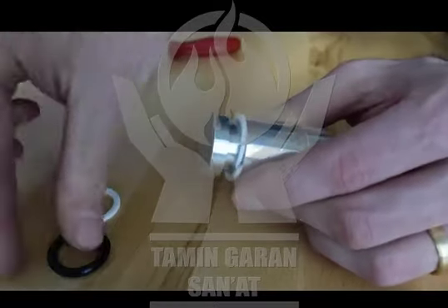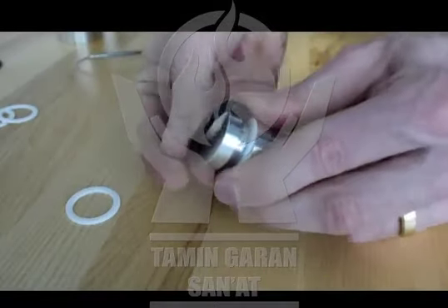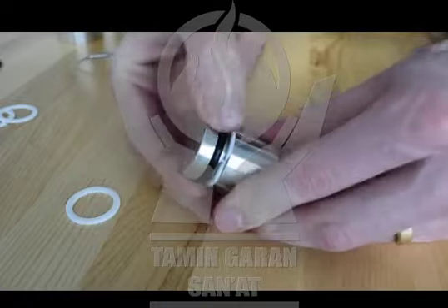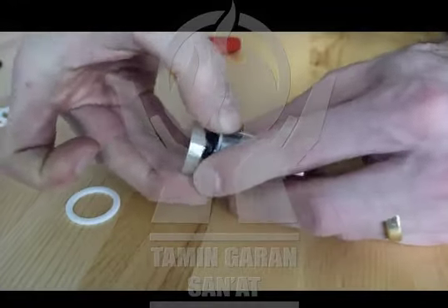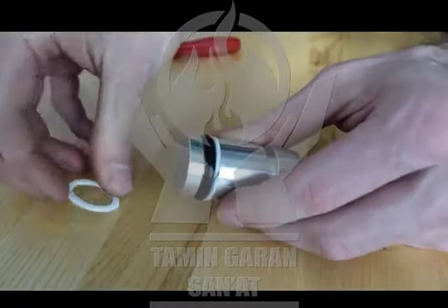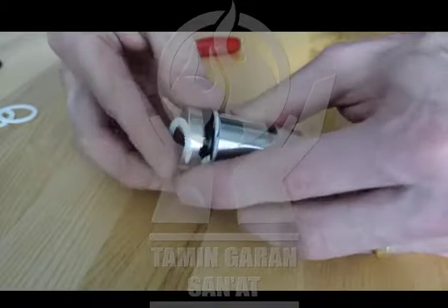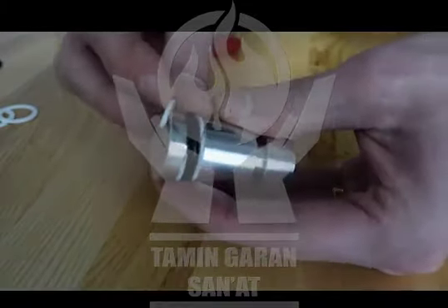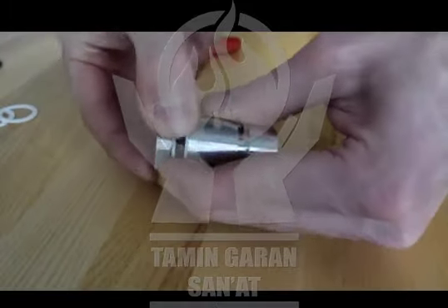They're made of a plastic like PEEK or Teflon, and they usually have a scarf cut to help you install them in the gland. Technically speaking, if you only had pressure in one direction, you could get by using only one backup ring. However, it's very easy to put the ring on the wrong side, so as a design for assembly precaution, if designing with backup rings, you should always design for two.